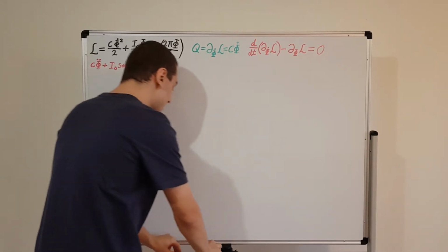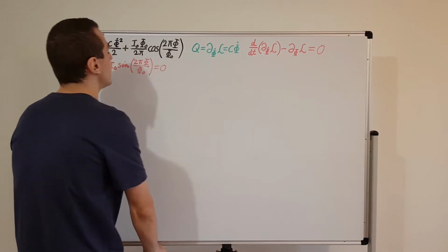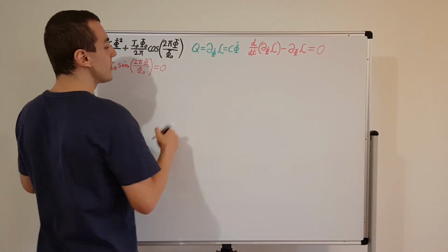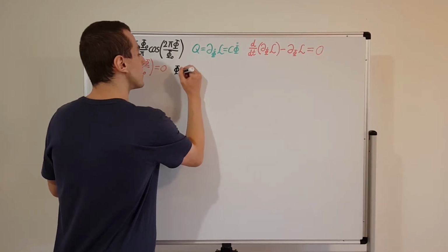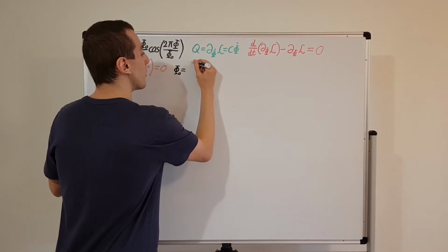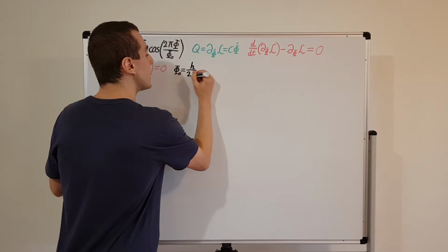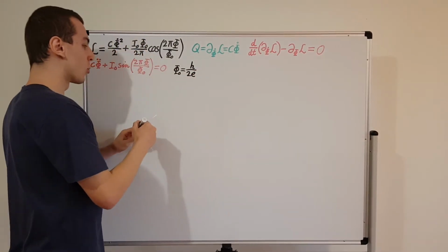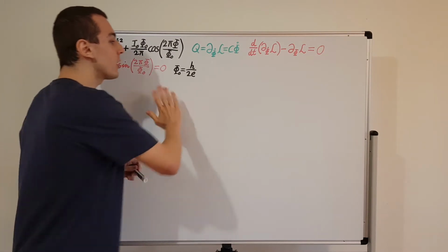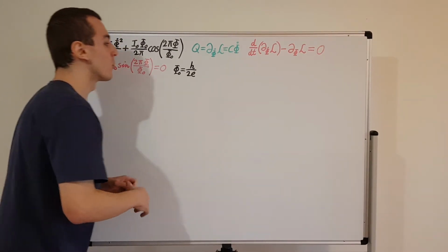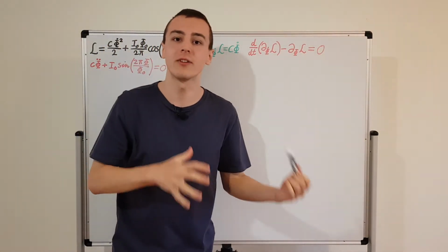Now, one thing I want to define over here is this phi naught. Phi naught can be thought of as the flux quantum. So phi naught is just a constant, and it is equal to Planck's constant over twice the charge of the electron. We're going to be seeing 2 times e, twice the charge of the electron, appearing very often in expressions when we're looking at superconducting quantum devices.